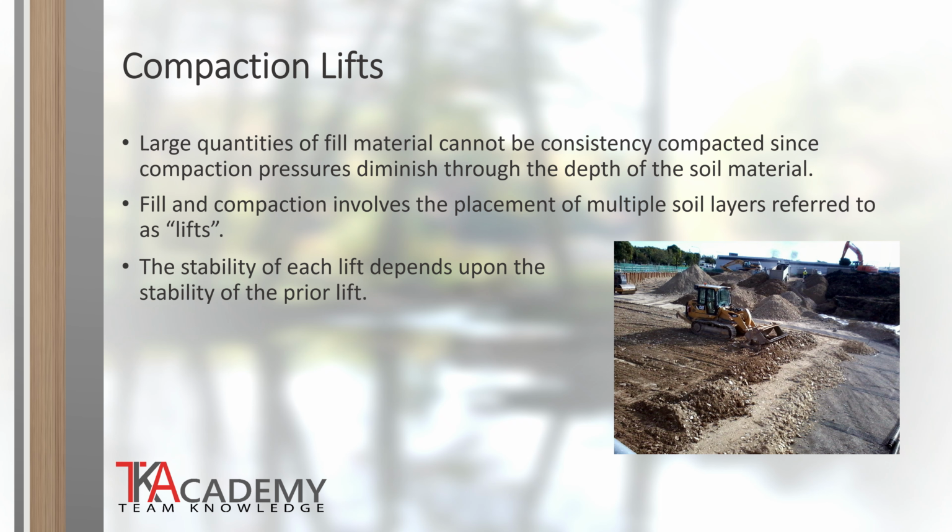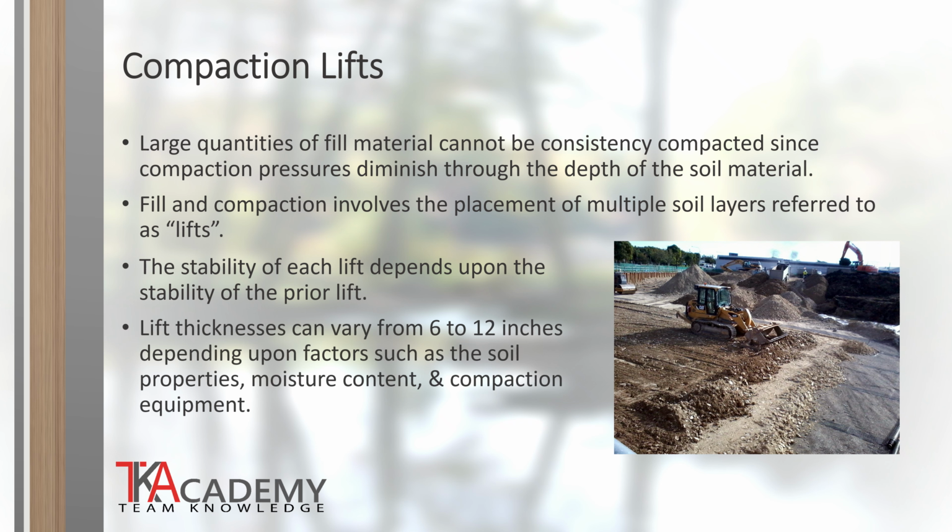Lifts do not always have to be the same material. In some situations, it is more desirable to have a material such as crushed rock on the subcourse levels to provide greater stability. This is often the case with road projects. The depth and compaction of each lift will depend upon a variety of factors such as soil properties, moisture content, and the compaction equipment available. Each lift is compacted separately to provide a suitable foundation for the next lift that is placed above it. In most situations, a compaction level of 95% is suitable for most structures to be built upon.